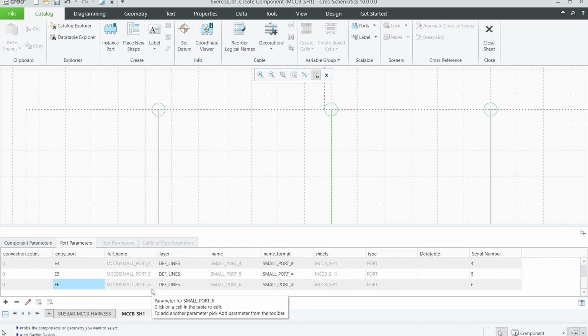Now we also have a concept called internal length. If there is a crimp plug over here, we need some extra wire so that it can be inserted into that crimp plug and pressed so that the connection is firm.